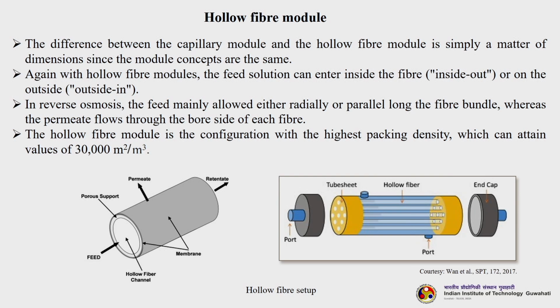Here the difference between the capillary module and the hollow fiber module is simply a matter of dimensions, since the module concepts are mostly the same. In hollow fiber modules, the feed solution can enter inside the fiber, either inside out or outside in. So we can have two different configurations possible here, just like our capillary systems.